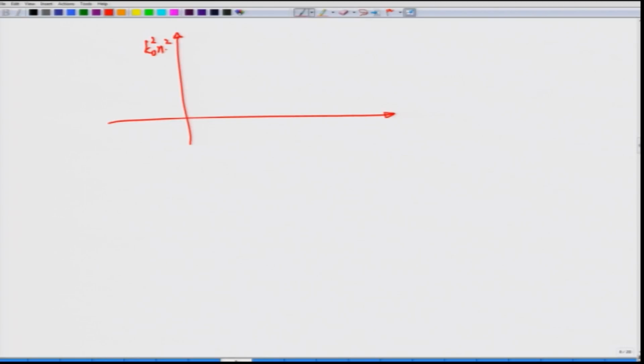If you look at the refractive index, the limit for beta would always lie between two things. For the guided case, it should lie between k 0 square n 1 square and k 0 square n 2 square. Now, if you look at the individual terms, k 0 square n 1 square of r, then you have minus beta square, and then you have finally minus nu square by r square.